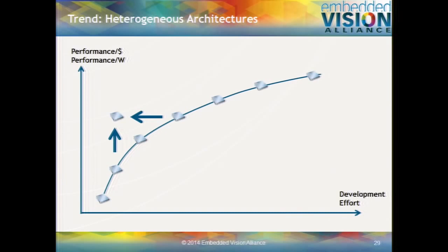These more specialized processors are harder to program than a general-purpose CPU. You have to know more, and you have to work harder to get an efficient implementation on these specialized architectures. But you get a more efficient implementation by doing so. So in the ideal world, 80% of your code is only consuming 20% of your processing cycles, roughly, and that can stay on the CPU because it's only consuming 20% of the processing cycles.